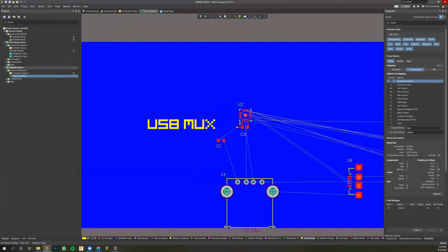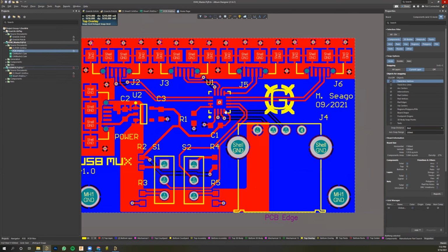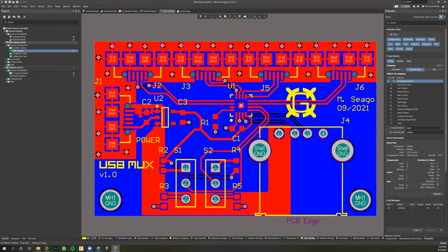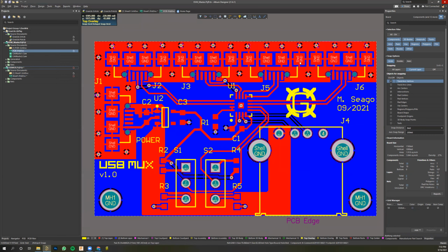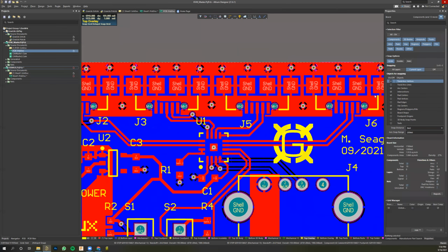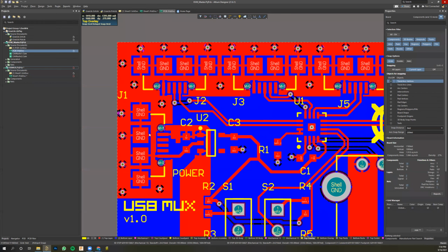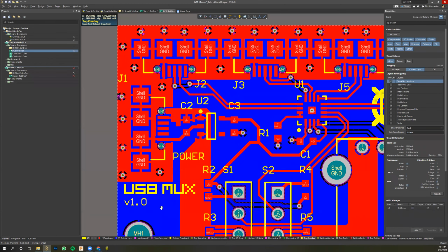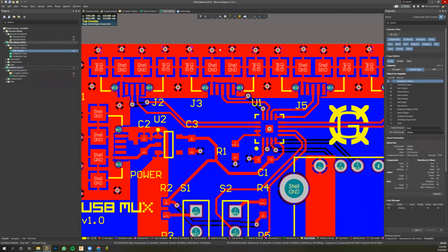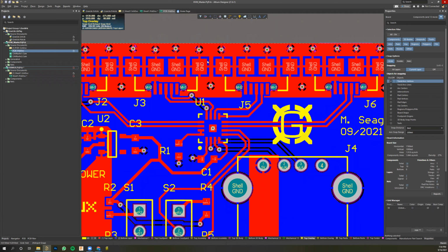So I think what I'm going to show you is this, and we'll just talk through it for a second. A few things going on here. All these are our micro USB connectors, and they have big ground connections and all that. What I've done is this whole red polygon here is one big ground polygon. Because it's not the primary ground connection, remember we made the polygon on the bottom to be that, I've put a whole ton of vias to connect this top layer polygon to a lower layer polygon. And again, if you have any questions at any point, please butt in.